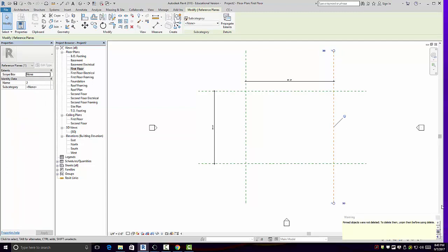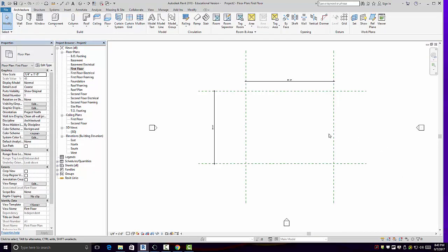Earlier versions of Revit, it wouldn't even let you. It'd fuss at you and say, I'm just not doing that. So you have to unpin it to move it, and that's a helpful tool. So you're going to use that to keep your overall dimensions fixed. Got me? So that's push pin.